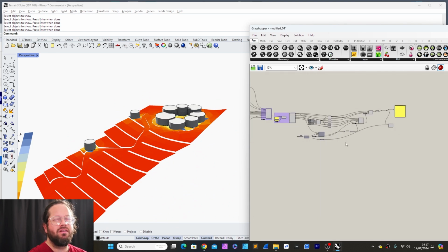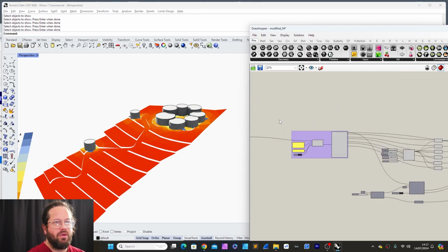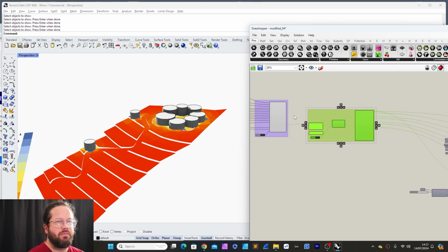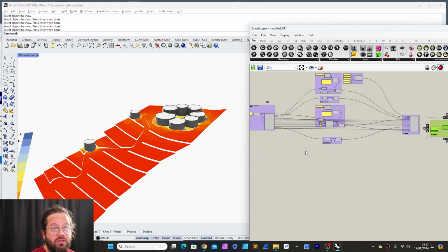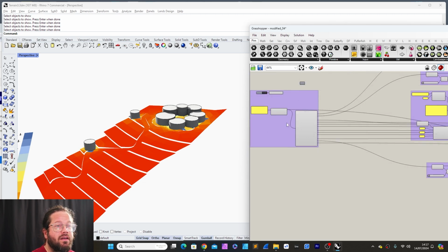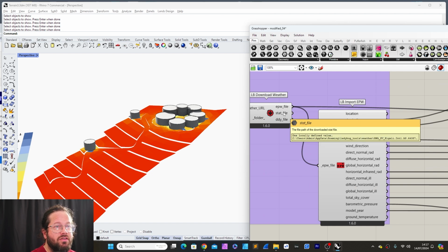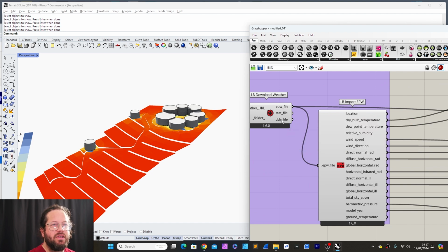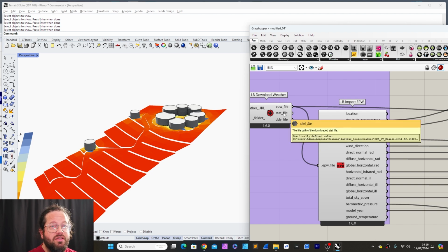Now, how can we analyze a bit more? What can we take out of this? Is there another way to look at it? We haven't really, because we used some components from Dragonfly, but if you have weather data which is very close to your site, then you could analyze something which is called the design days. Design days are basically days with a very average kind of data set. They are very average for this specific location. There are also statistic files.